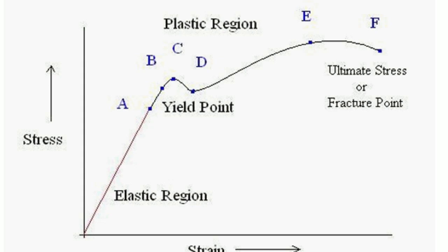Before, the strain was increasing and the stress was also increasing, but after point C, the stress is decreasing but strain is increasing. So what is C to D representing? Yielding starts in this portion, and there is a drop of stress at point D directly after yielding begins at C. The point D is called the lower yield point and C is called the yield point.